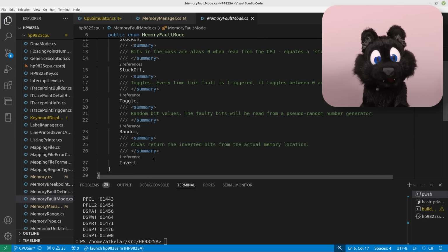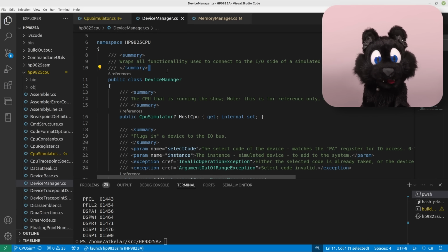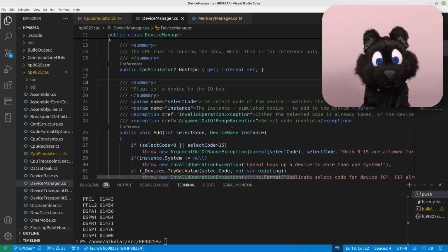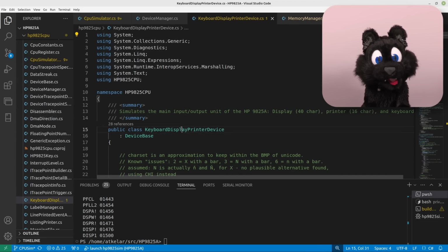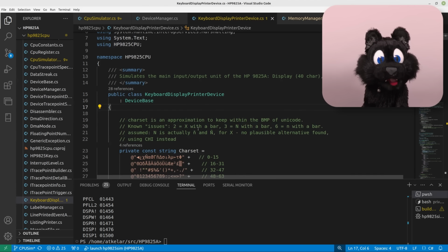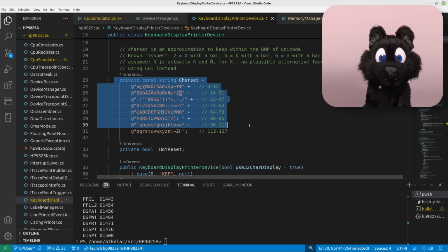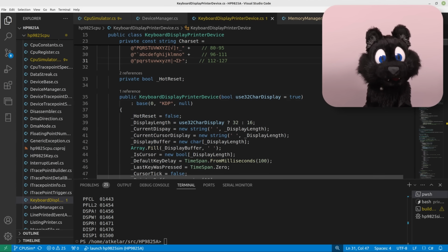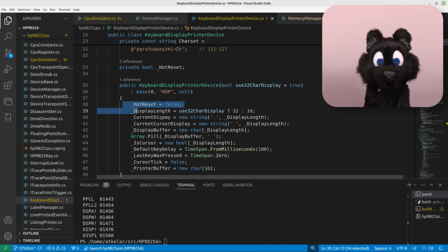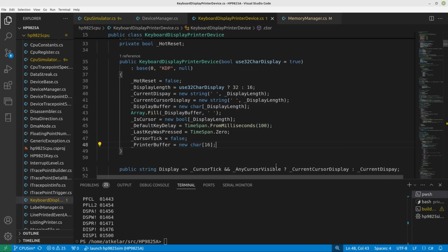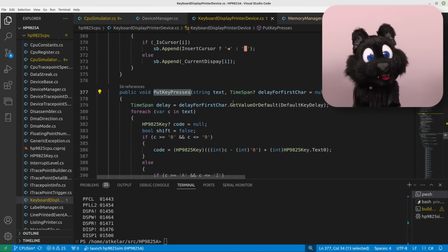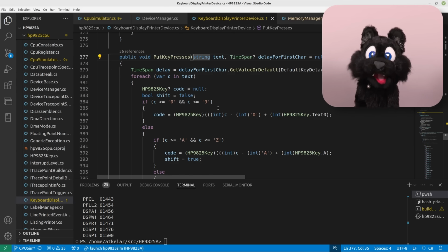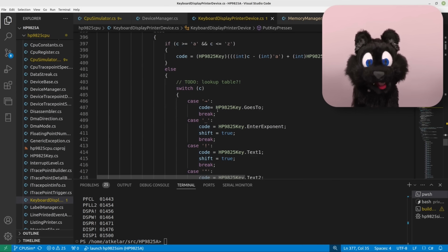Instead of hard coding the output to the CPU directly, I created I/O devices and basically connected them via the same logic with the CPU as the real devices would have to follow. Here I coded up a version of the KDP, which includes key presses to trigger an interrupt and provide the pressed key upon request. Enough feature creep already? No? Good, cause I'm not done yet.